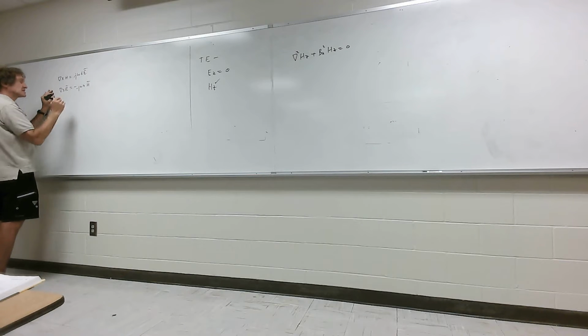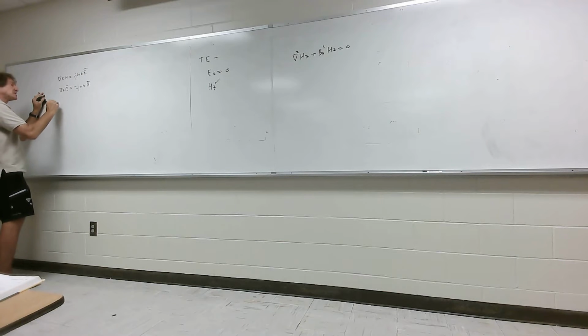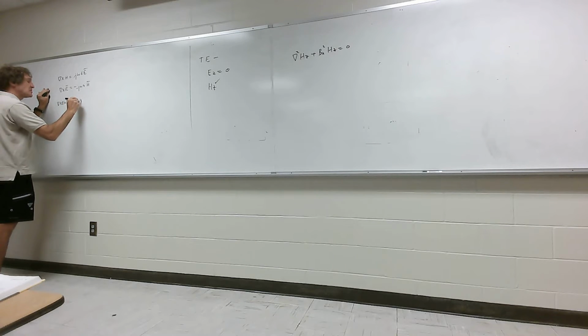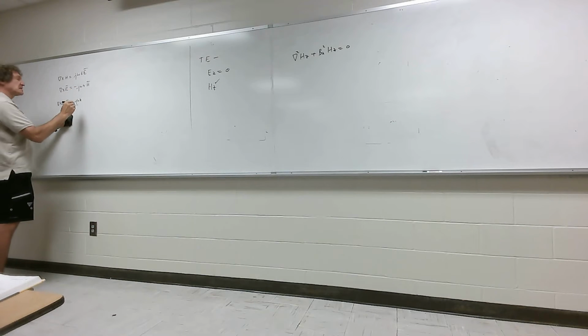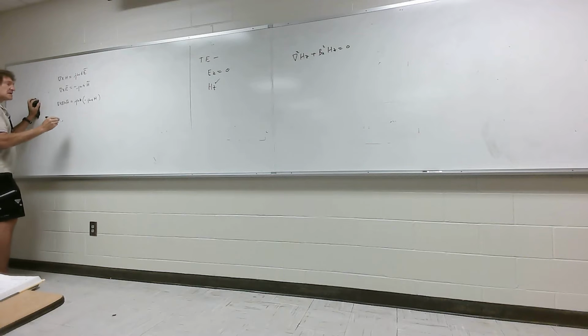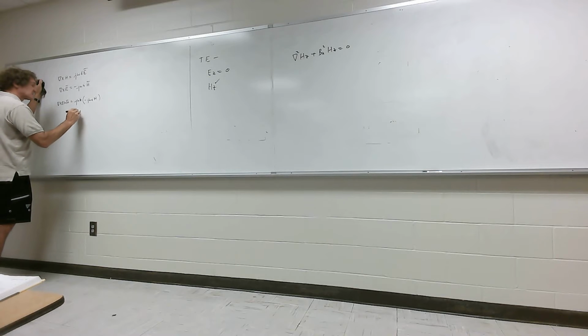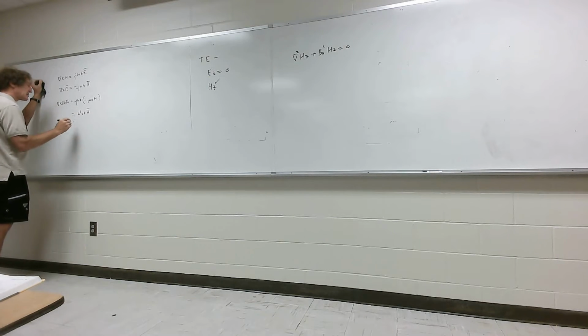Then you have the curl of E equal to minus j omega mu times H. Now we get one equation with only one unknown, but this time we want it in H, not E. Do you follow me, class? So we take another curl of that equation. We get the curl of curl of H equal to j omega epsilon times the curl of E. There's my curl of E, so I put it in: minus j omega mu times H. Then j times j is minus 1, and with the minus sign it's plus 1, so I get omega squared mu epsilon times H equal to this.